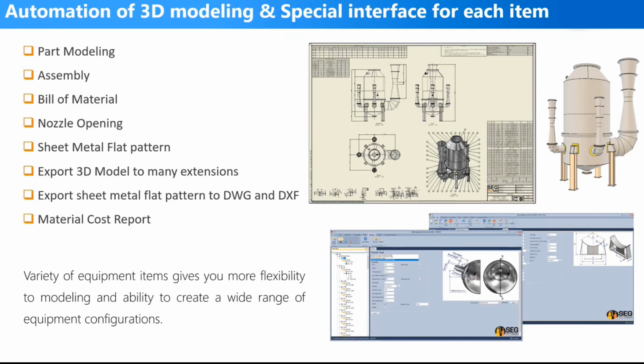For the storage tanks, you will be able to generate radial roofs, ranged plate roof, dome roof, bottom plate, and annular plate. You will be able to add some attachments to this storage tank, like spiral stairs, clean-out doors, and manways. Both clean-out doors and manways are related to the API standard. And if you would like to make some modifications by hand, by changing the dimensions, you will get a chance to do that by selecting an option to define the dimensions manually.